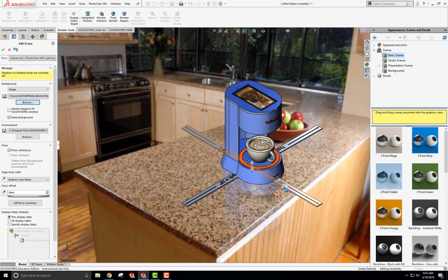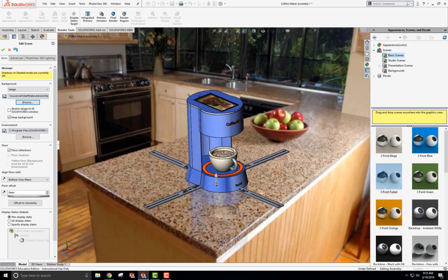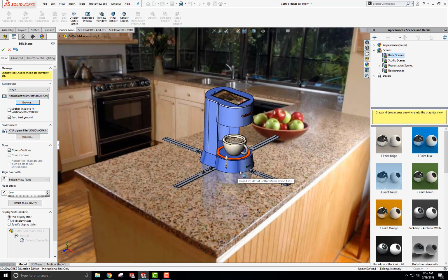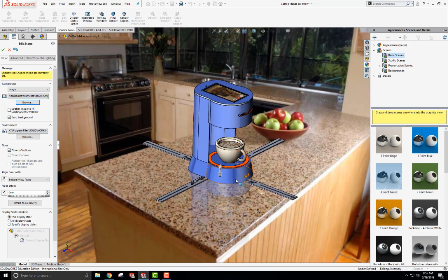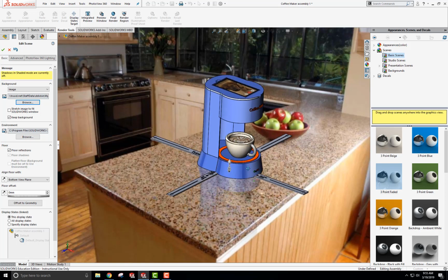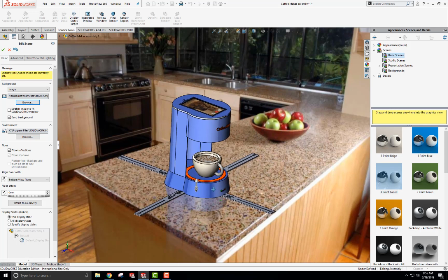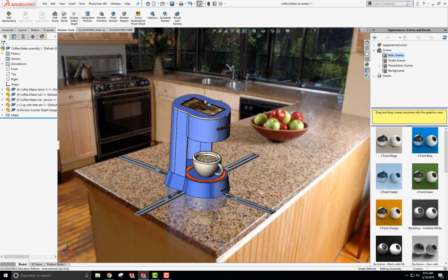So now I'm going to use the Control key plus a scroll click to move this around, rotate it like this. You can zoom in and out to enlarge it or make it smaller. And the idea is that it should fit on the counter, basically, like this. And so as I use the Control key, scroll click, right there where it fits the counter more or less, for like a 25-inch counter, that's the size it should be. Okay, I'm going to check mark that.